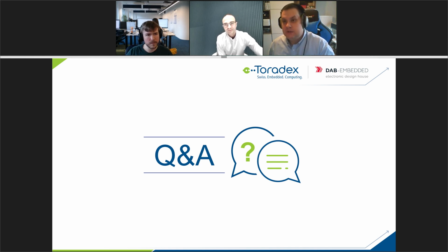I will say in this way that NVIDIA versus Aquila, I see a benefit of Aquila only in the image vision pipeline. Why? Because the owning cost of NVIDIA software is much higher. You need to have a partner who does the calibration for you, while all source code of GStreamer plugins is available. There are no hidden blocks, so if you want, you can play with the calibration data and tune the video pipeline by yourself. On TI, almost everything is open source.